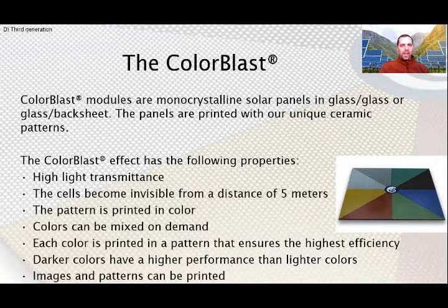Darker colors have a higher performance than lighter colors. Images and patterns can be printed. It has an efficiency of 75 to 90% of a standard module, 80 to 150 Wp per square meter, depending on the color.